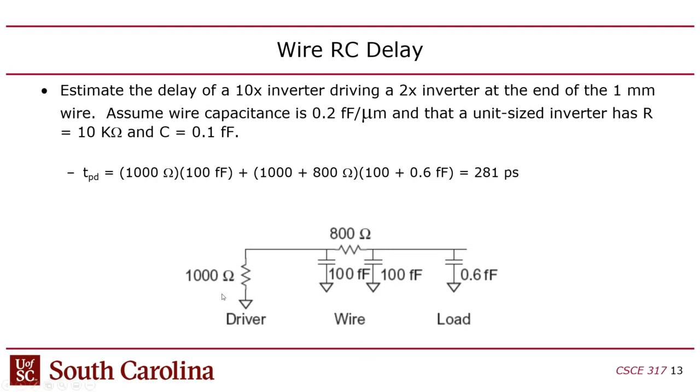Now you might say, wait a second, doesn't the output of a gate also have capacitance, diffusion capacitance? Yeah, it does actually. For whatever reason, I got this example from the textbook, and this particular example didn't say to include any output capacitance, but that's something that I might ask you to include on the exam or on the quiz. So just be aware of that. But in this case, it's kind of simplified. It just says that essentially it's a 1,000 ohm driver.